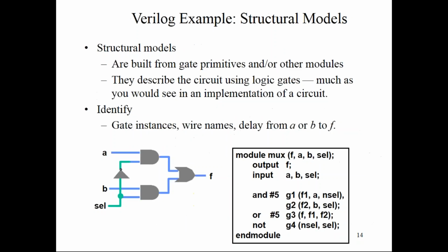But if it's a 2-bit wire, then we have to define it. If it is more than 1 bit, we must define it. Or we can write the NOT gate first, and then AND and OR gates, right? Or else do we need to follow this order? No, actually it is a concurrent statement only. So in whatever order you define your hardware, it will automatically synthesize. That's not an issue here.